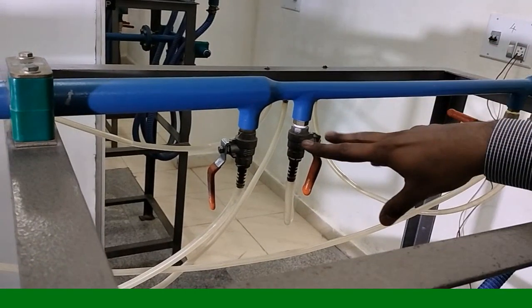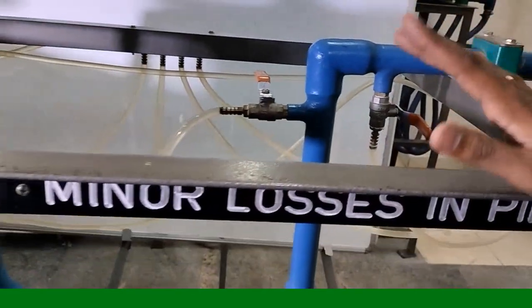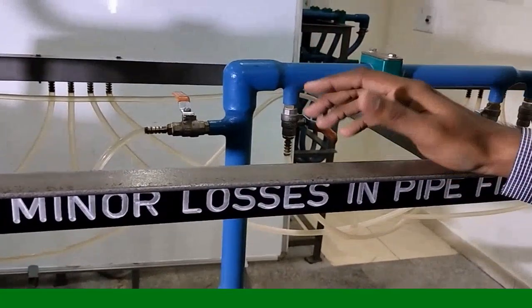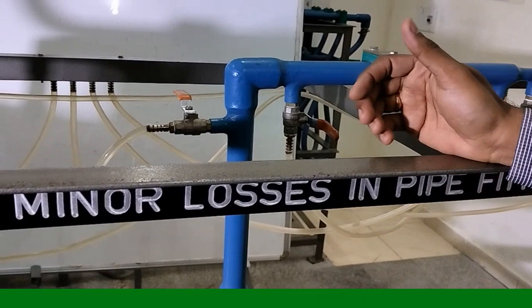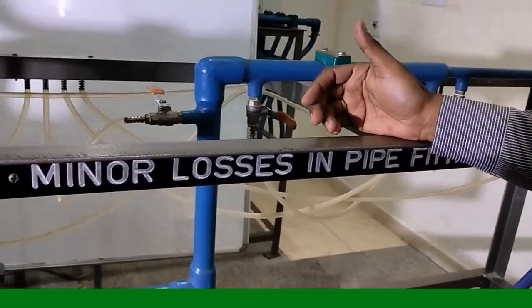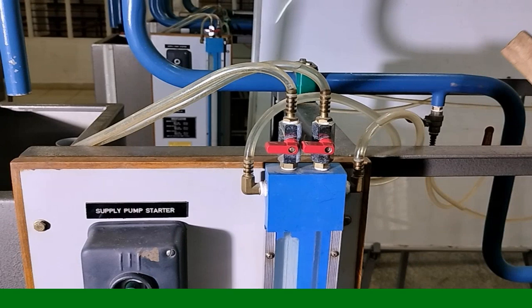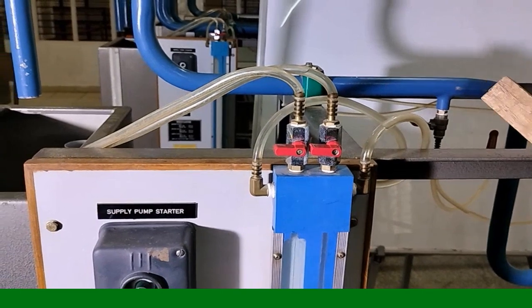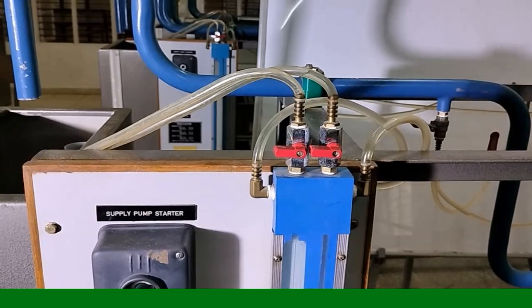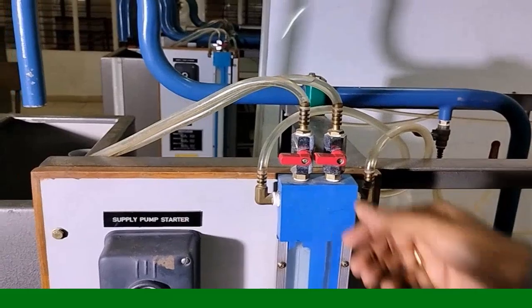One set of trial I am going to show, and the calculation is also shown in the next part. Minor losses as water flow measuring devices. During the first reading of all the experiments, we have to remove the bubbles. Just open these valves for some seconds. After switching on the pump, the bubbles will come out. After the bubbles come out, take the readings for more accurate values.